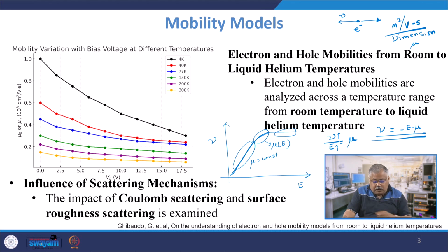So the rate of increase is not there. Had there been no scattering, this would have gone like this. As you move further down, you see your velocity is becoming constant. Why is velocity becoming constant? Now the force which you are applying and the reverse scattering phenomenon are exactly becoming equal. So velocity becomes constant, your acceleration goes to 0, and you have a fixed velocity of the charged particle. Exactly like an analogous case of rainfall falling onto the earth, there is a critical velocity after which a constant velocity is reached. So this is the basic fundamental principle of any mobility model which you see.